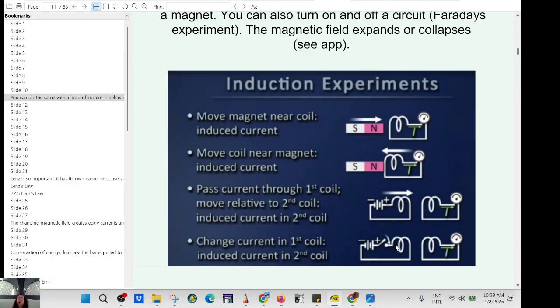You're going to induce electricity, and the appliance will work on its own before it turns off. So you have to be careful, because if you open it here, you can have a spark. Because the magnetic field will collapse, you're going to induce a voltage in the circuit that you open, and you can have a spark. It's like the old car; the spark plug works this way.